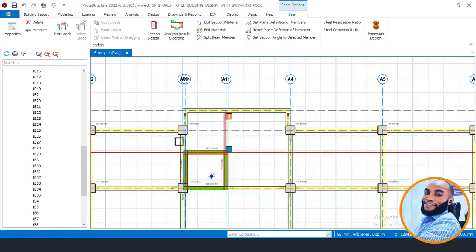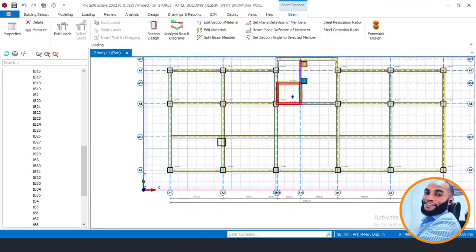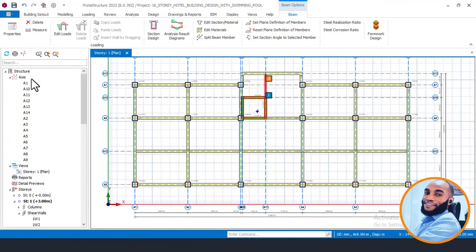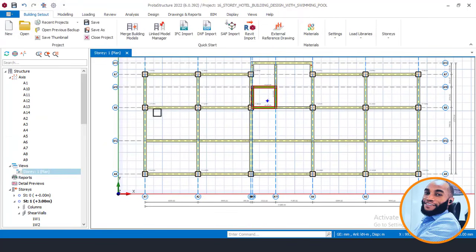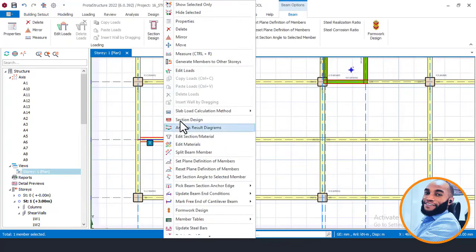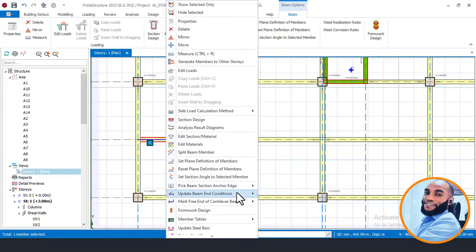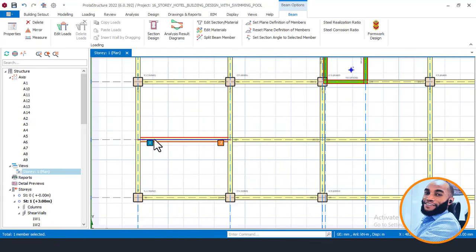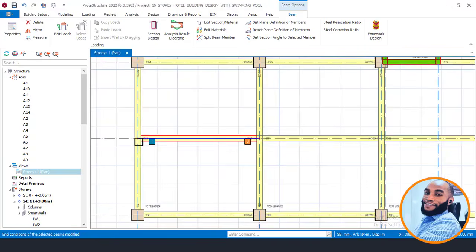So that's fine. So again, right now I'll have to place what they call hinging. To hinge your beams on this software, the first thing to do is to hinge all the ends of the beam. So I'll come here, click here, and then hinge at this end here by doing Assign, Hinge at I end. This basically is an I end. So I'll click here and then say Hinge at I end. I'll say apply to selected beams. You now see that there will be a hinge.